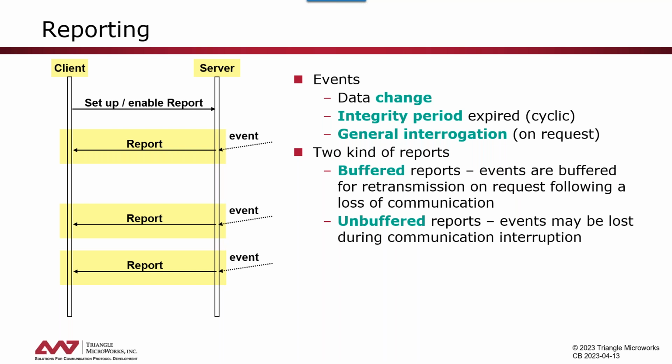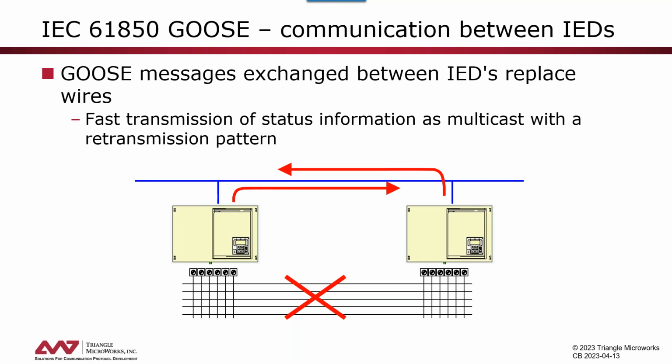So much about reporting. Now, as I mentioned before, IEC 61850 added two protocols to the MMS, which is the vertical communication, and one of these is GOOSE. GOOSE basically is intended as communication between devices to implement protection and control schemes and more or less replace physical wires that we had in a classical substation. We had binary outputs where we routed signals, then we went on binary inputs from the other relays, as an example, blocking signals. Now the communication mechanism called GOOSE, or Generic Object Oriented System Event, can basically replace these wires.